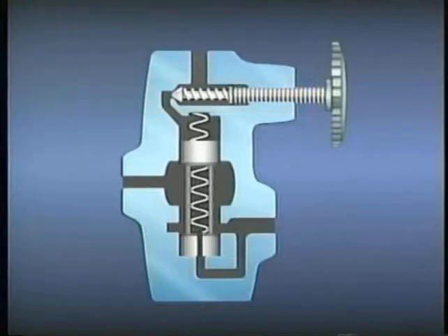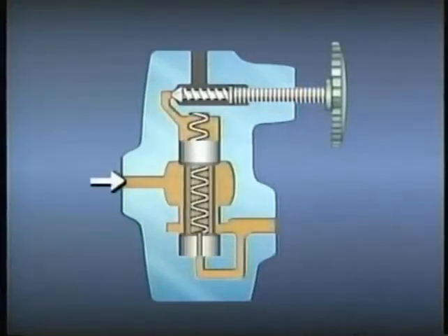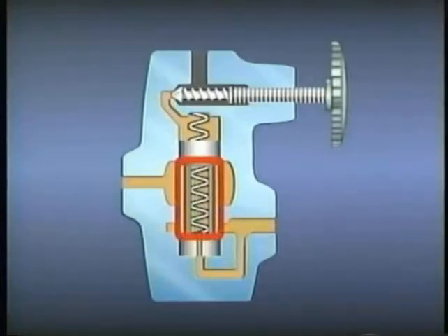When supply pressure is less than the desired outlet pressure, fluid enters this inlet, flows around the spool, and leaves through the open outlet. Although fluid is present inside the spool and at the pilot valve disc, at this point, the pilot valve and spool have no impact on the valve operation.